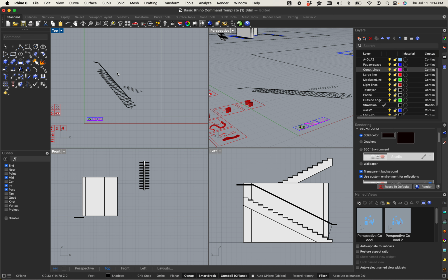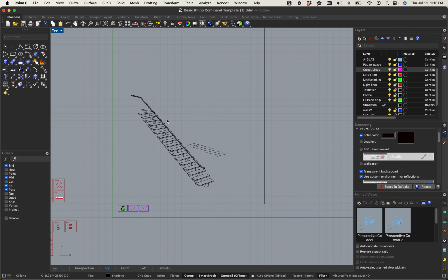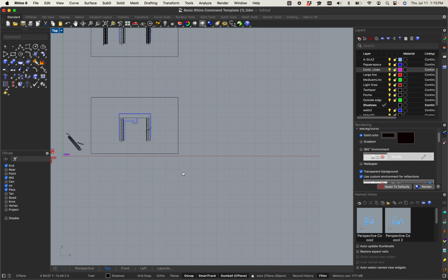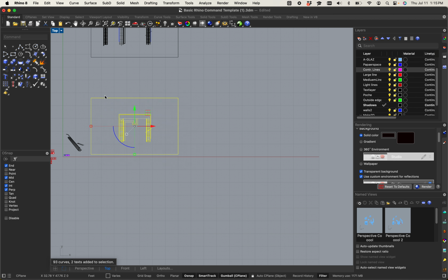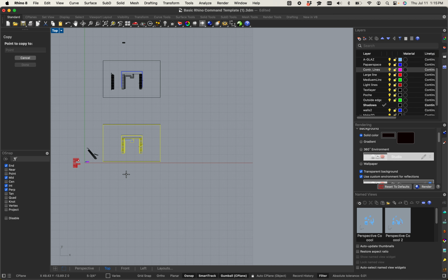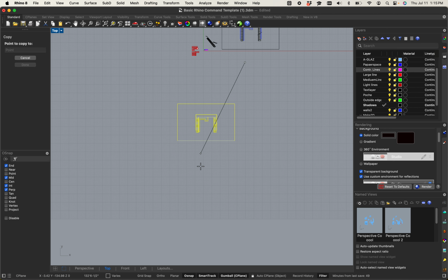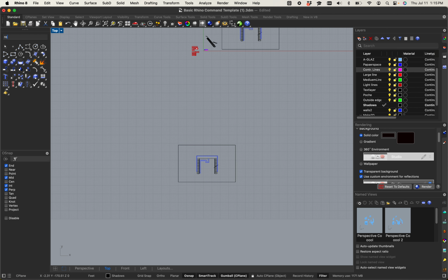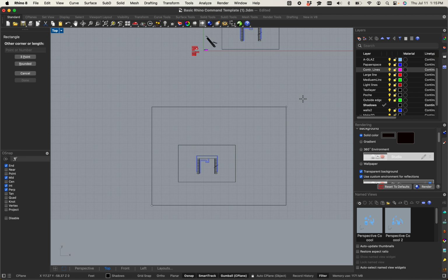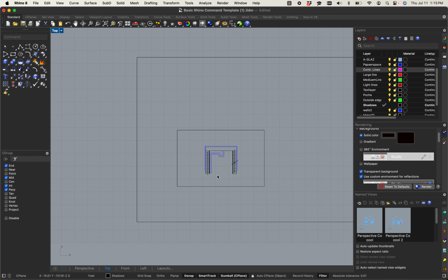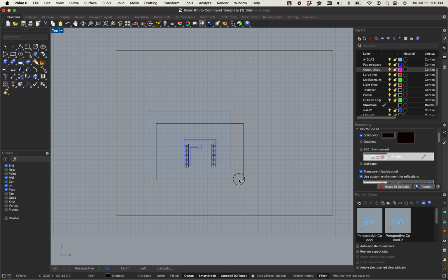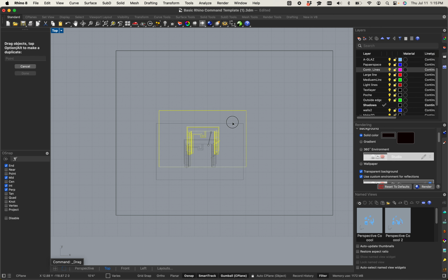Now, how would I go about drawing a 2-point perspective digitally? Same as your analog, right? Shouldn't be too difficult there. Now, just like the analog, it's going to require some things. I'm going to need my elevation, and I'll need my floor plan, and I'll have to set it up just like I would on my desk, right? I even like to make the desk, right, and just call this the 11x17 piece of paper and almost act like it's a real thing.